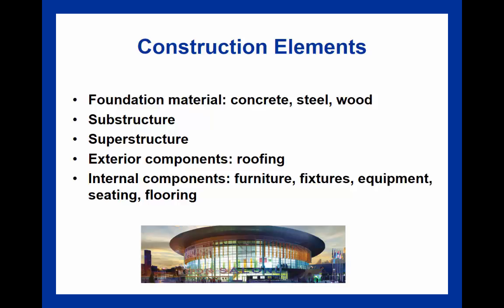This is a process in which the contractor can determine the presence of rock, organic materials, and potentially dangerous materials in the soil for that facility. The water table could be tested, etc. So this is pretty comprehensive earthwork. Then that area is going to be cleared so that the building area, which is going to be 5 feet beyond the limits of the proposed structure, can also be ensured.